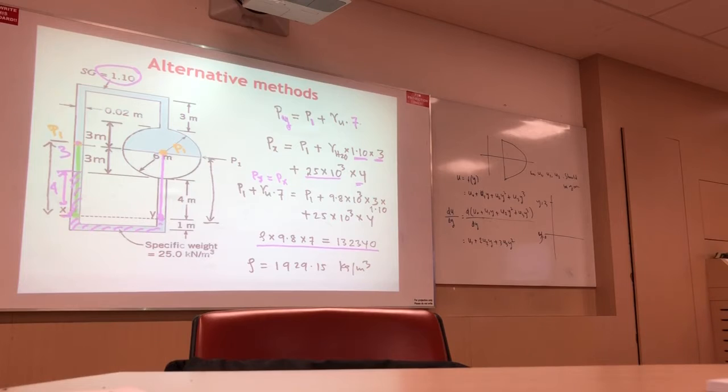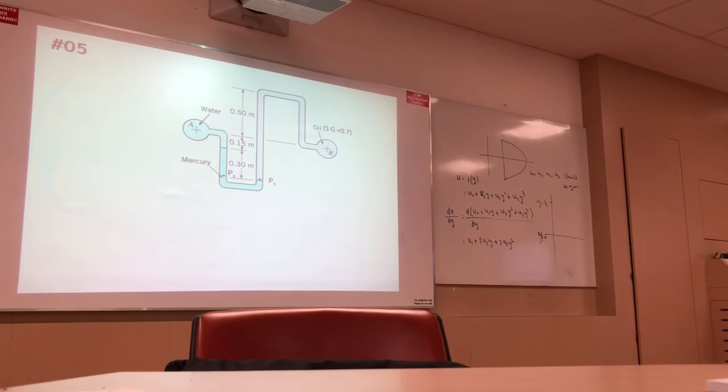Question 5. This one also same thing. This one I show you the easiest method, and the traveling method you do by yourself. At that point the pressure is PA. Am I right? At that point what is the pressure? PB. At that point? PB. Yes, because of the same fluid and same height. Good. Done. And we choose the line at that point because all effects are present.